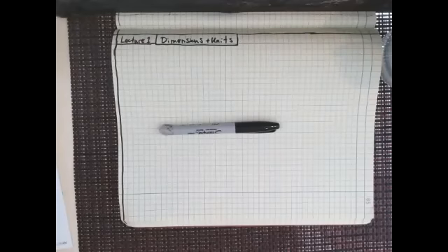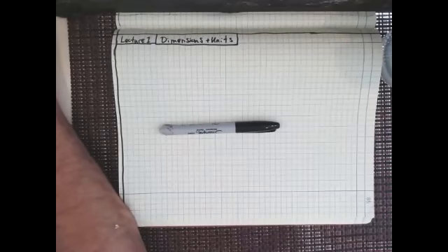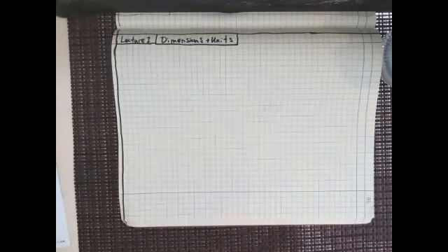But this also extends into your experimentation later on. Because if you use dimensional analysis and similitude, extensions of a real understanding of dimensions, that helps you decrease the number of experiments you would have to run to find relationships between various variables in engineering equations. I'll give you a good example of this. The Reynolds number, which is a dimensionless number for fluid flow analogies. Coefficient of lift, coefficient of drag. There's a lot of things. So we won't really look at dimensional analysis and similitude.